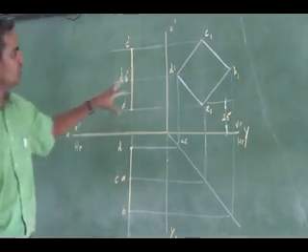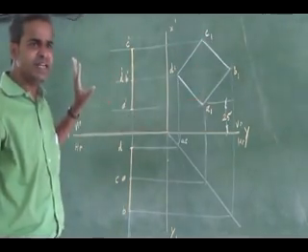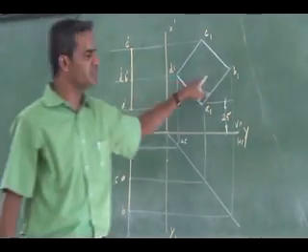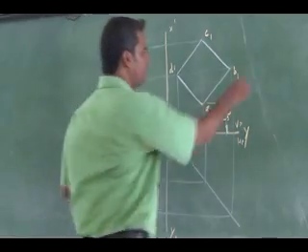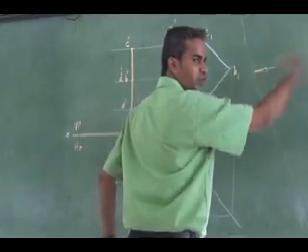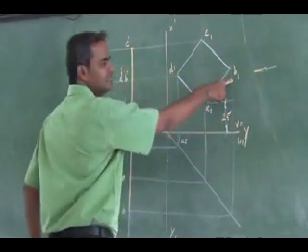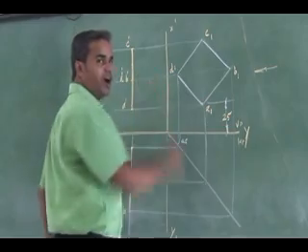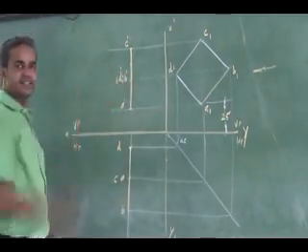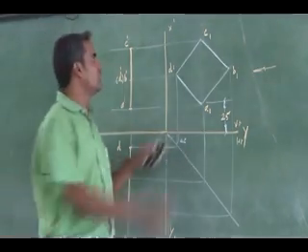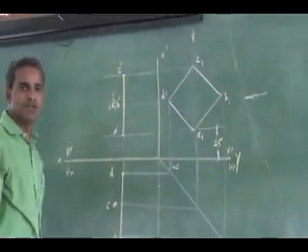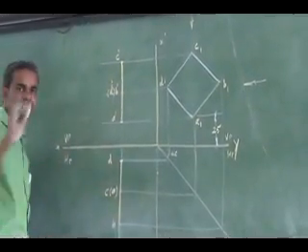Which one will be inside the bracket and which one outside the bracket, you have to define. See here, from the side view, this is the way I am looking for the front view. Which corner is hidden? D1 is hidden, D is hidden. For the top view, I have to look at the side view from the top, and the hidden corner is A.